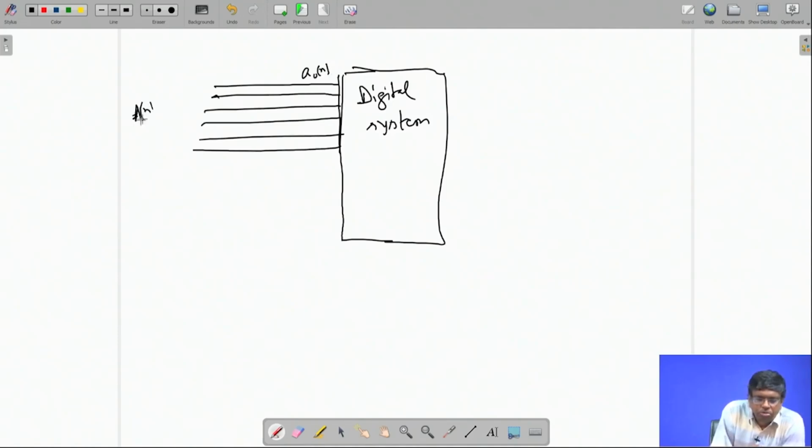I have got input data An, whose 6-bit representation is like this: A0n, which is a binary bit, either 1 or 0, then A1n, A2n, A3n, A4n, A5n. So, A0 to A5 at the nth clock they go in. All the 6 bits, because data here I am saying to be 6 bit, are going parallelly. So, bit parallel or word serial structure, I mean for A.